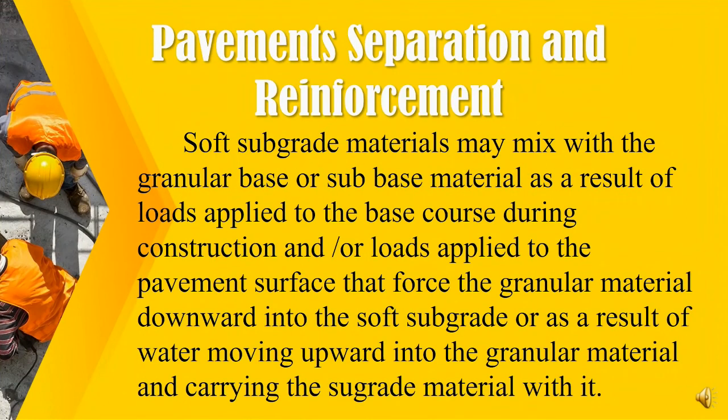So next is pavement separation and reinforcement. Soft subgrade materials may mix with the granular base or sub-base materials as a result of load applied to the base course during construction or loads applied to the pavement surface that force the granular materials downward into the soft subgrade, or as a result of water moving upward into the granular materials and carrying the subgrade materials with it.